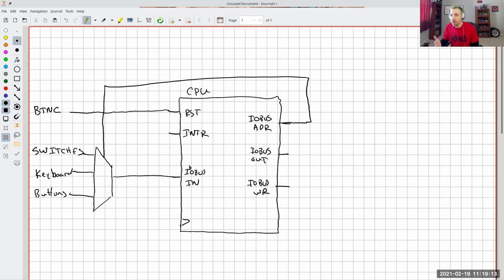And so if I want to read from switches, I'm going to give it an address of 11.0.0.0.0.0, and so that in my mux has to be an option where I'm going to choose which one of these gets put to where. This mux is ultimately where I pick what goes where in my memory mapped IO. So this is where I would give switches that specific address, and maybe my keyboard or my buttons some different address.